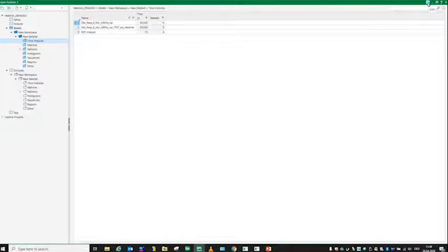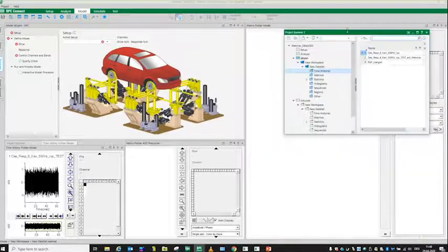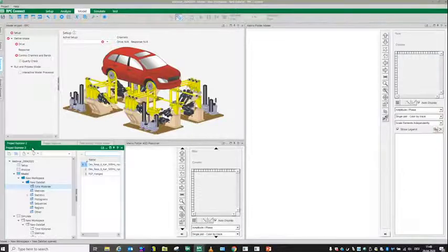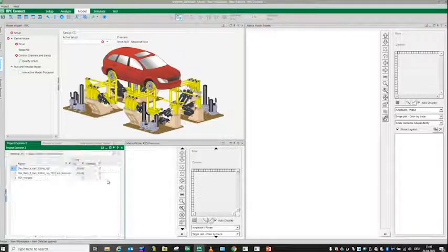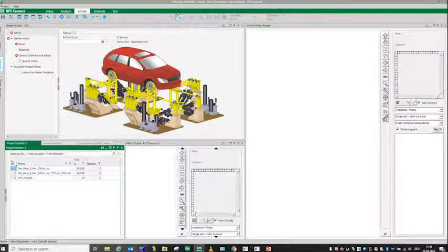It is important because if I have, let's say, the window docked, in this case, let's move it, for example, to the same place where the time history plotter is. So we put it here, so I have less space here. Less space is bad, and less space needs more efficiency in looking at my files. So if I click on that vertical splitter here, it will show me everything I have here. So if I have removed my columns and have only the columns which are important for me in that Project Explorer, I can have an efficient view on looking at them while clicking on this slider here or while just choosing the columns I'm interested in.